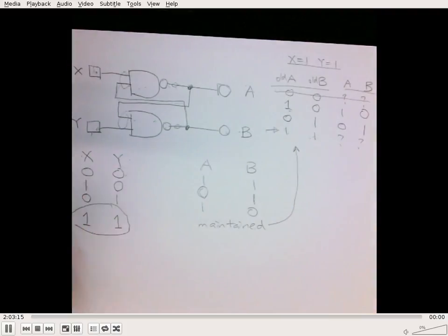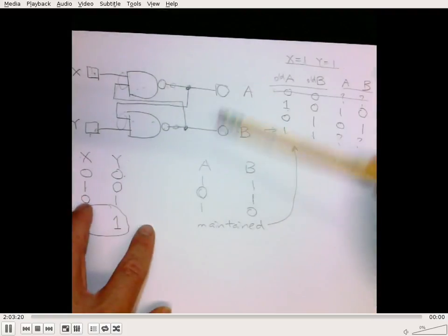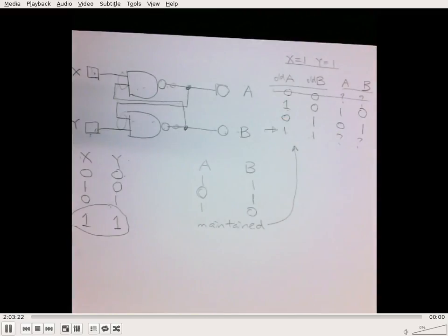Oh, so that's why it is still an oscillation, because it's not an oscillation between A and B, it is an oscillation of both A and B being 1s, and then they both become 0s, then they both become 1s, they both become 0s. That is the oscillation reported by LogicSim. So does it just loop then? It is a loop, yep. And the frequency of that flipping and flopping depends on the latency, because the latency of the gates determines the exact amount of time it takes for the 1 to become a 0 and then for the 0 to become a 1.